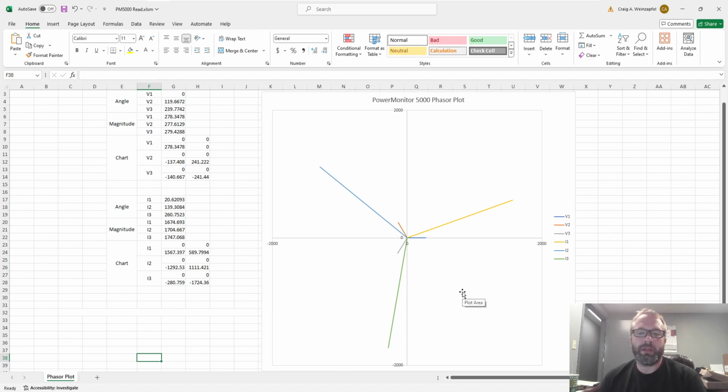And one thing that really allowed us to find this was to take a look at these phasors when we pulled the data in, and we saw that B and C were physically 120 degrees off of where they each should be. And once we found that and moved it, power factor read normal. Some other parameters we looked at were the sequence current, which was actually reflective of what we would have expected on the positive sequence current, and that's because all of our voltage phasors were correct, and the rotation was A, B, C,